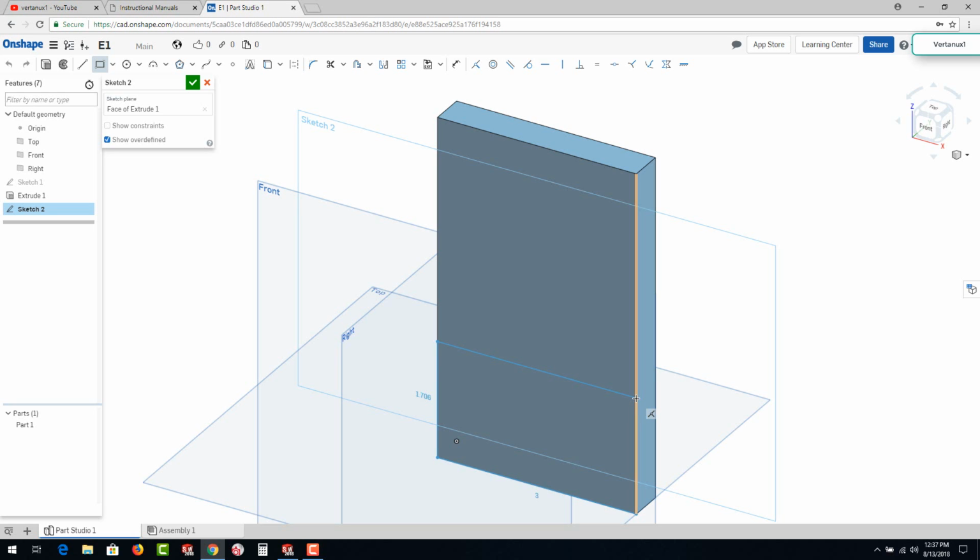You'll see those on a lot of CAD systems nowadays, and essentially there's two types of constraints you could add. There's numeric, which are basically dimensions, and then you also have constraints, or relations as they're called in some systems.